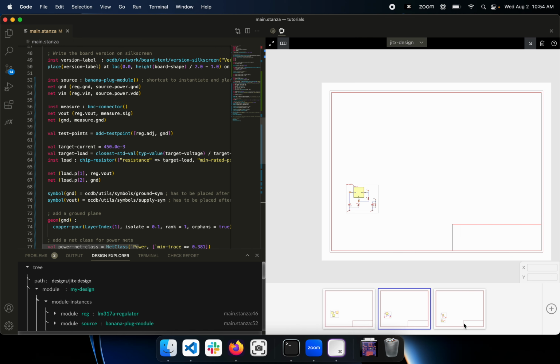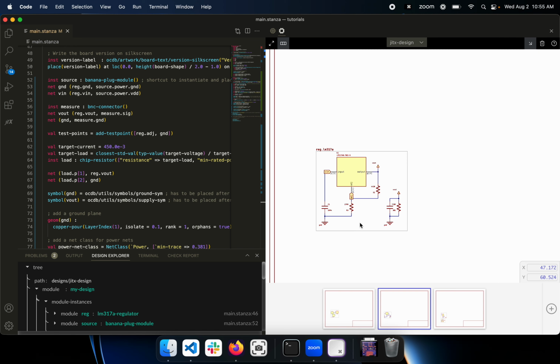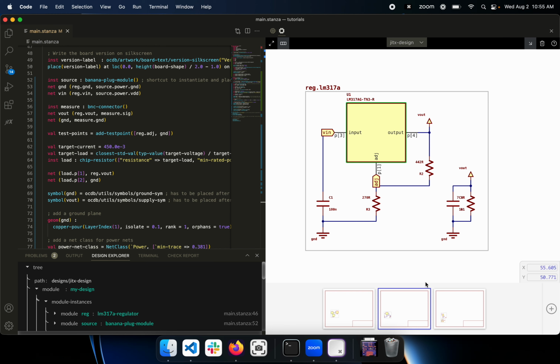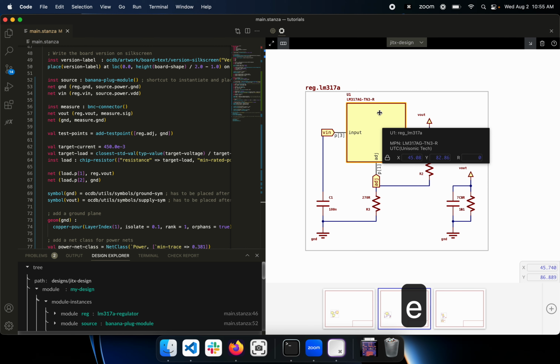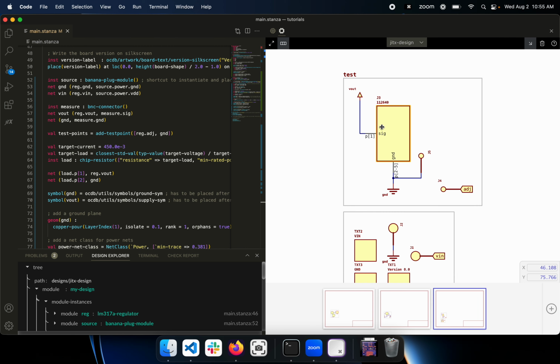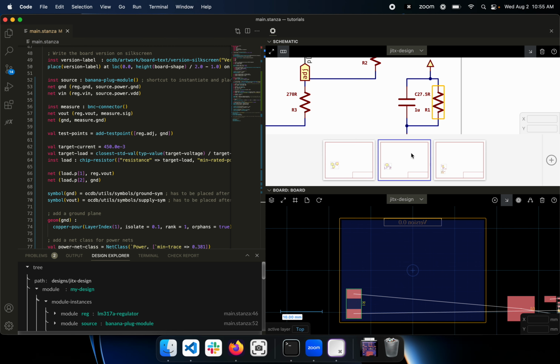So I just have this set up here. Page 1, we've got a hierarchical schematic, not too much going on there. And then it's split up our groups across pages. So here is the regulator. Press E, and notice I've got screen recordings of my keyboard capture so you can see what's going on. So that is our regulator. And then on the next page, we've got the connector and then some just test points. Okay, I notice you can double click on here, it's all cross-linked.